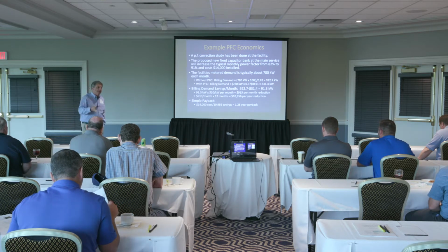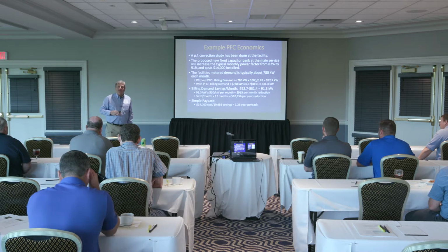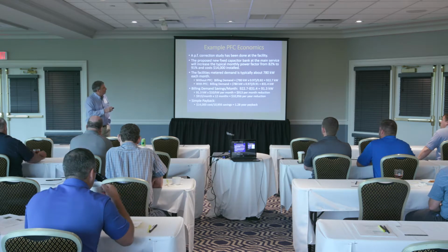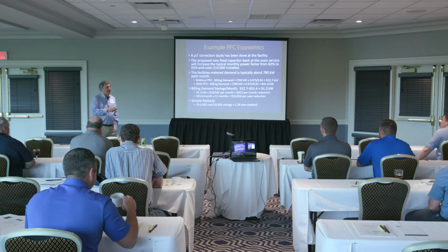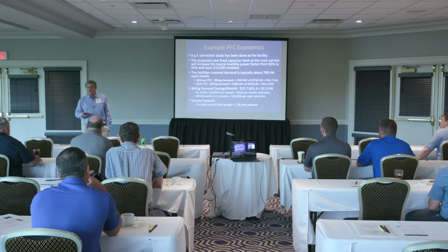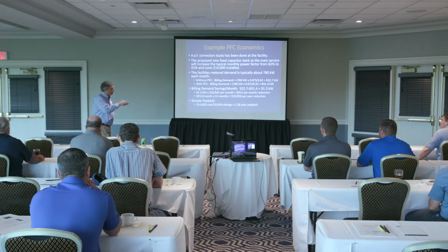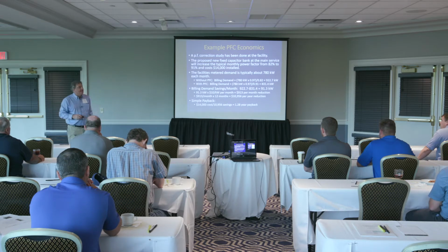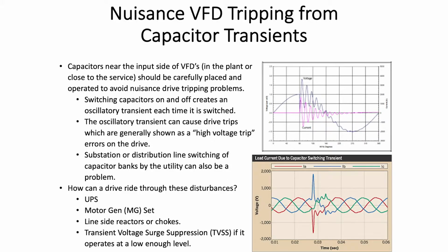Most utilities have set their power factor adjustments up such that, when I talk to consultants all over the country, probably 95% of the time it's cheaper for the customer to do this than for the utility to do this. So this tends to be one of those things that lots of customers look at and find the paybacks are really good. So now, a couple of other caveats about power factor correction.